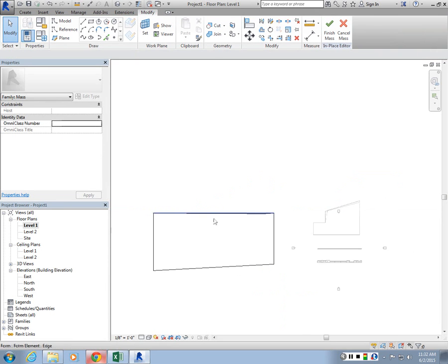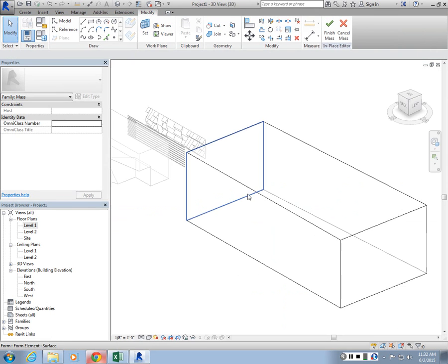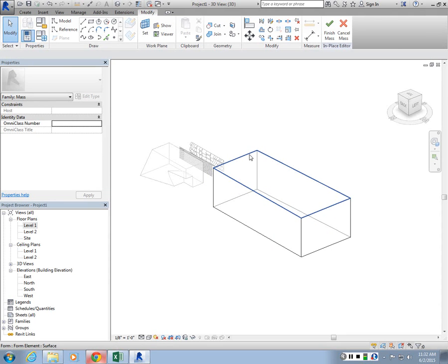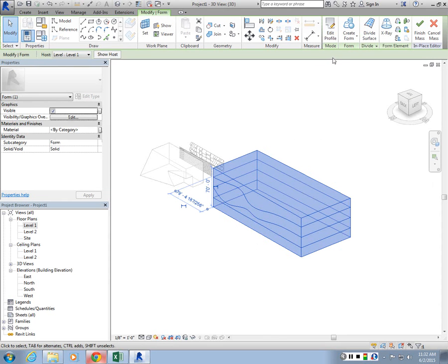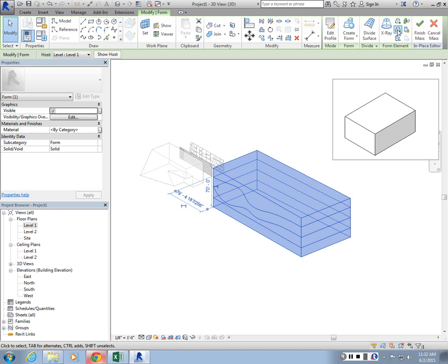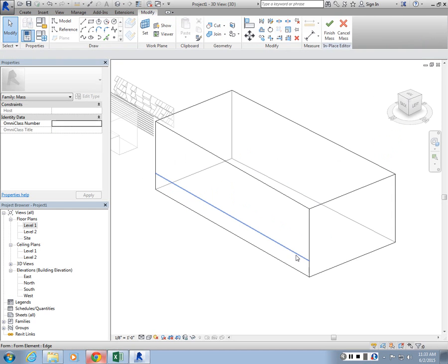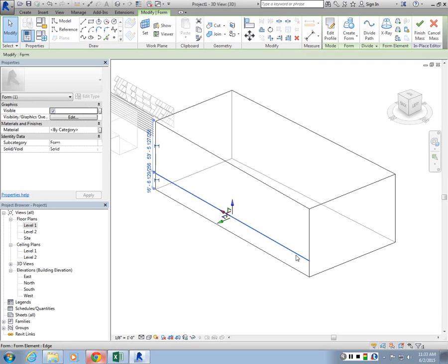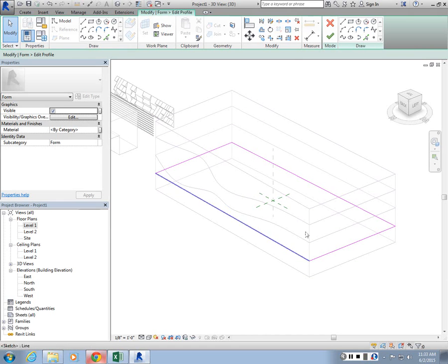Sure. So select the massing. Once you're inside the massing, go to form element and do add profile. And when you choose a level, it adds one. Then basically choose one of the profiles you want to edit, like this guy, and then it shows you under the context ribbon the edit profile option. And when I do the edit profile, it highlights the profile, and I can just delete and override the element, right? So I can make this go this way, and maybe for the last one,